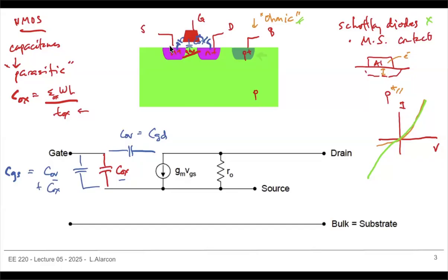So you do get a certain capacitance due to the overlap, but we'll see that it is relatively small, and that depends on the perimeter intersection between the source and the gate, and the gate and the drain. Right. So it's only dependent on, for example, the width of a transistor. Right. So if you look at this in 3D, going into the screen, that's going to be the width of the transistor.